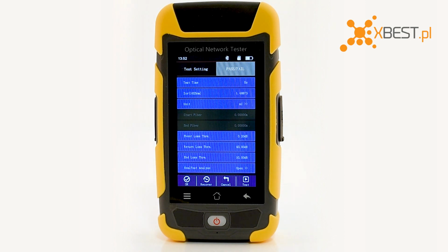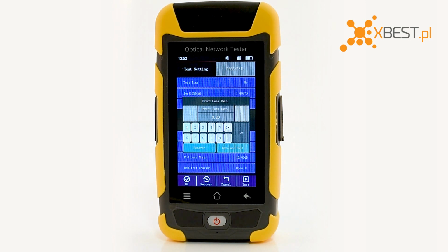Unit parameter allows you to select between available measurement units. Event loss threshold lets you set the threshold in decibels for loss, non-reflective events. When you select smaller threshold values, the tester makes a trace with less noise. To do this, the tester makes more measurements to be averaged or uses wider pulse widths. Thus, smaller values can possibly increase test times or dead zones.